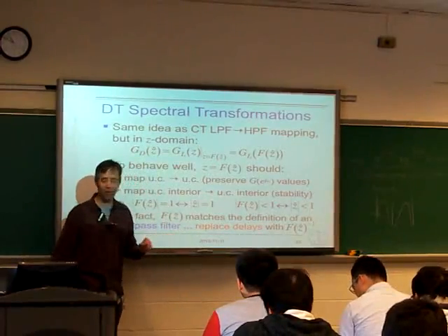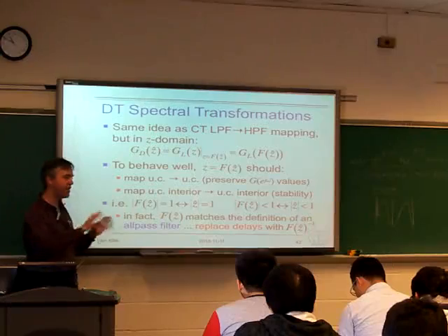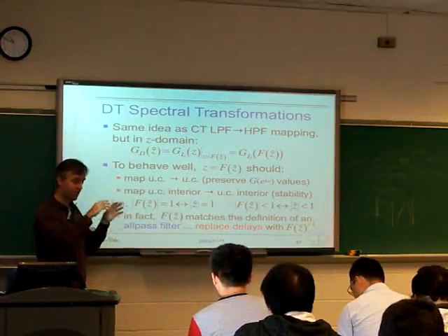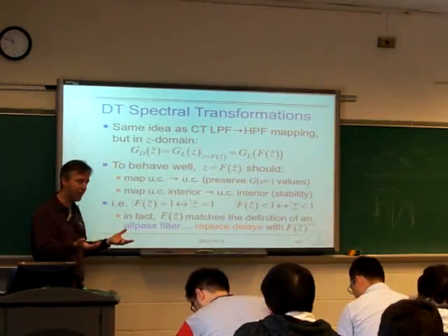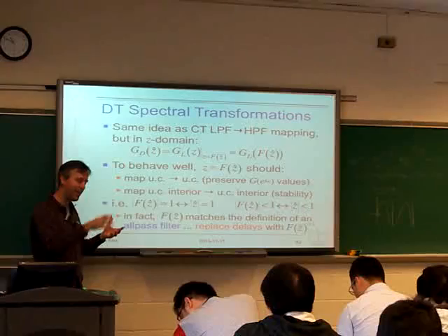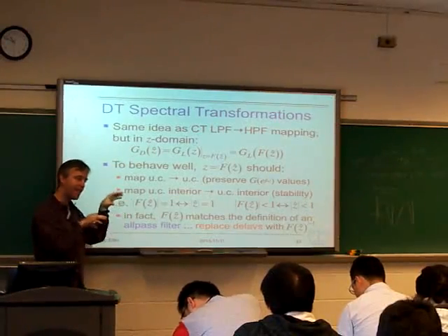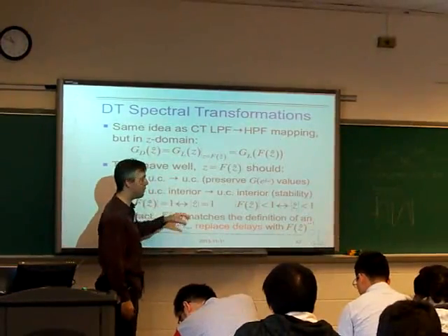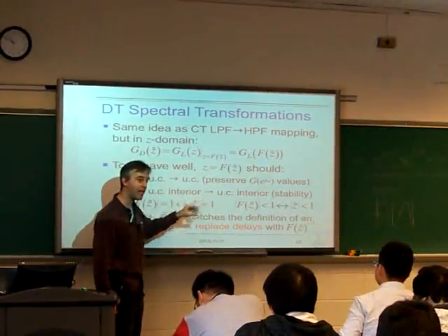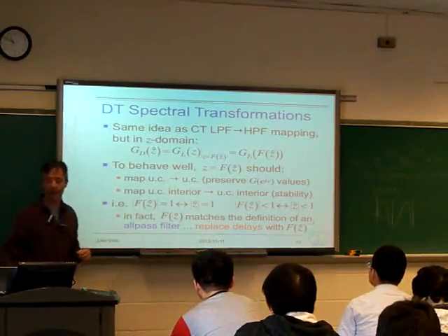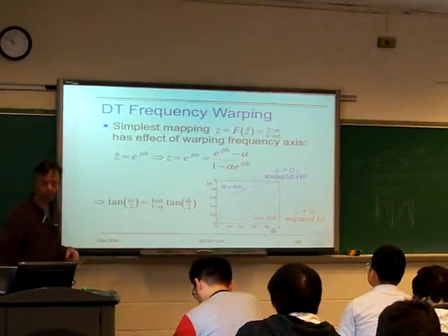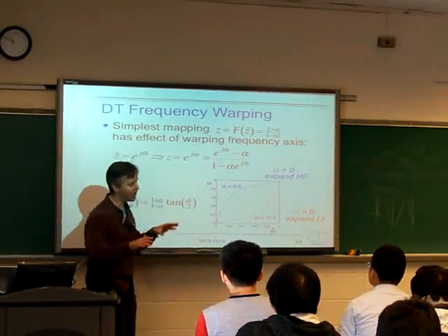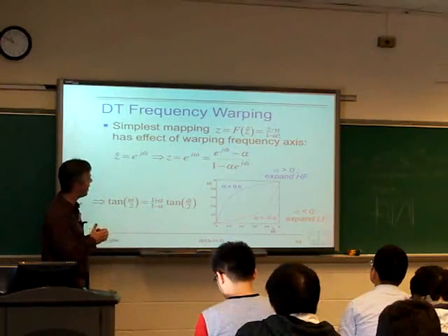But it's kind of cool that you can do it, and it's just this nice way of tying together the block diagram representation with the actual z to the minus 1s, which is just like a notation, and saying, no, that really means something. It means that you can build the system out of delays, the delays z to the minus 1, and if we replace that z to the minus 1 delay with some equivalent mapping of the z-plane, then we also get a valid z polynomial. All right, well, I don't want to stress that too much, just sort of let you know that it's there.